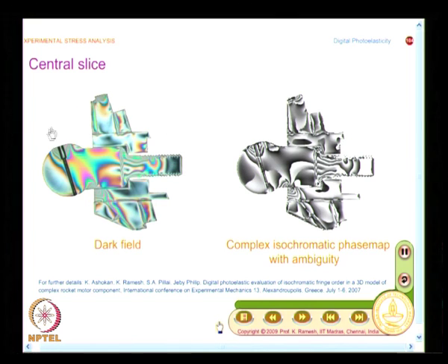And this also illustrates, you have seen a 3-dimensional model. From a 3-dimensional model, a 2-dimensional slice is taken. See, I want to analyze a 3-dimensional problem. So, I need to take a 3-dimensional model and then I apply the loads by following similitude equations and also the model to prototype relation. I find out what is the actual load that I should apply, and do the stress freezing. Once you have done the stress freezing, stresses are locked. From that, whichever portion is of importance, you make a slice and then apply 2-dimensional photoelastic analysis to interpret the data.